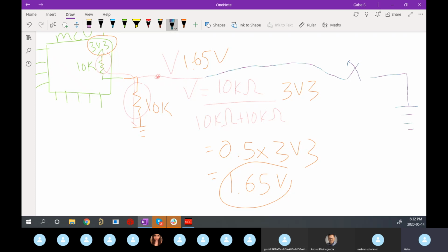And then when you actually do close this, you may even cause damage to some of your components because you're essentially shorting out this resistor to ground. It's definitely recoverable because all you have to do in software is just fix this. Or if you have access to the hardware, you can just unsolder this, but it's not going to help you if you have both by accident, for sure.